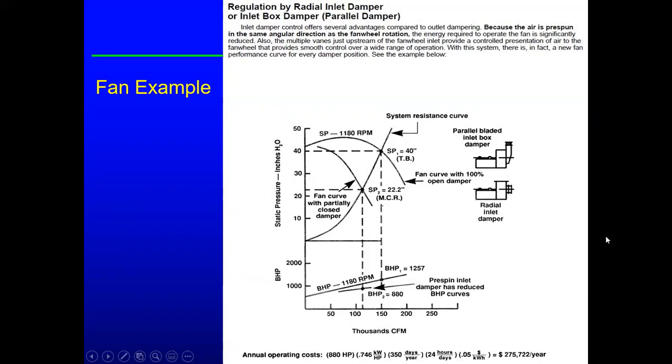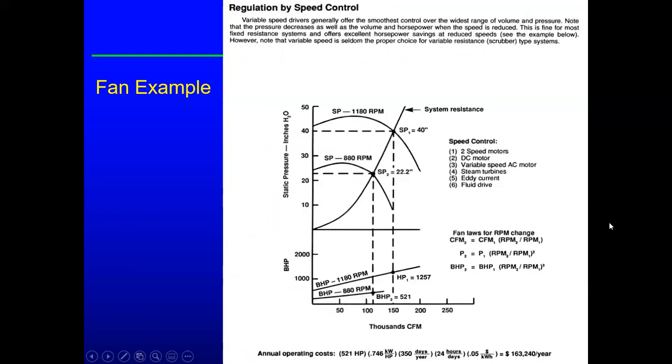Now, installation, because I think they need to have HVAC refrigeration. They need to have some air conditioning in the MCC, which you may not have or may not have enough. They require a good bit of space, which can be a problem. So if it's not designed in on the front end, you may have some issues with getting a VFD in there. At any rate, okay, now we're going to go to speed control.